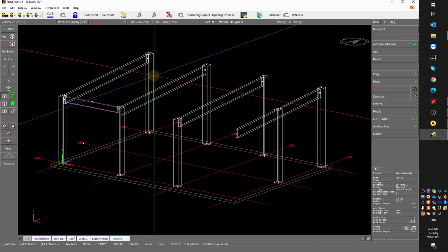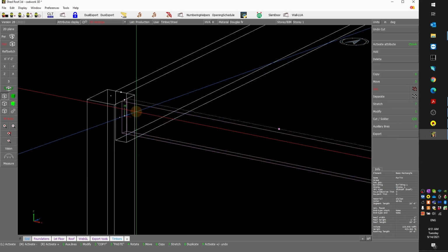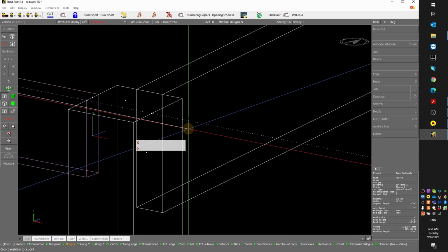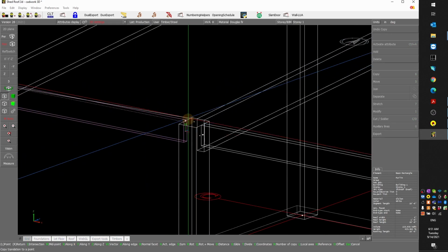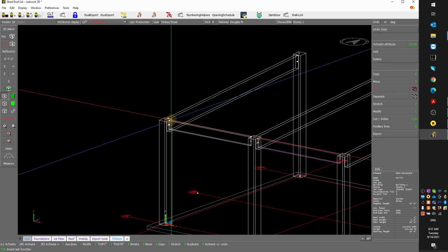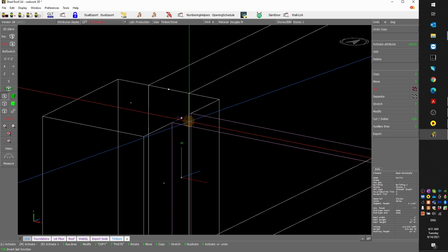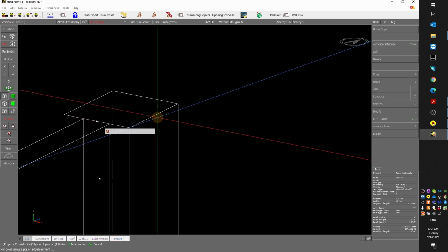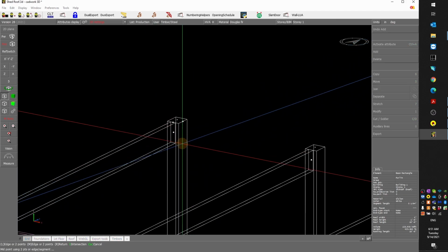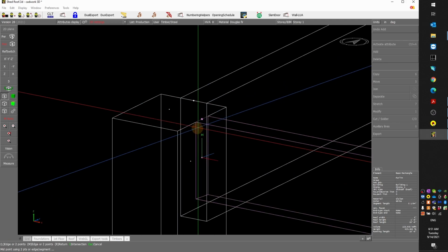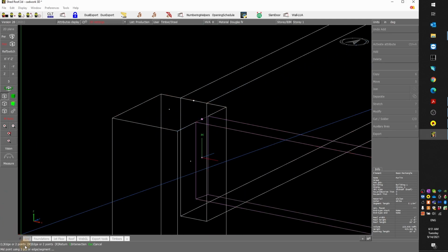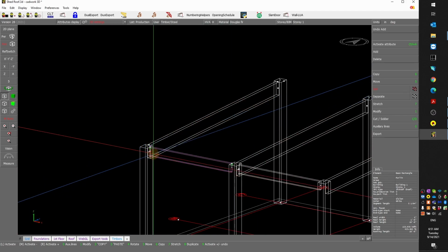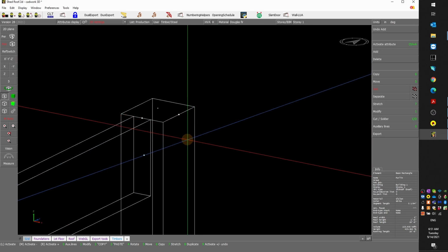Well, actually, yeah, let's copy it horizontally. So 6 in X, and I just left click here. My reference point was here at the back. Now I select through the center. I can find a midpoint here. There we go. So the part is still selected through the center. I'm still in the midpoint command. I can right click, and now I can copy this guy by pressing 6.